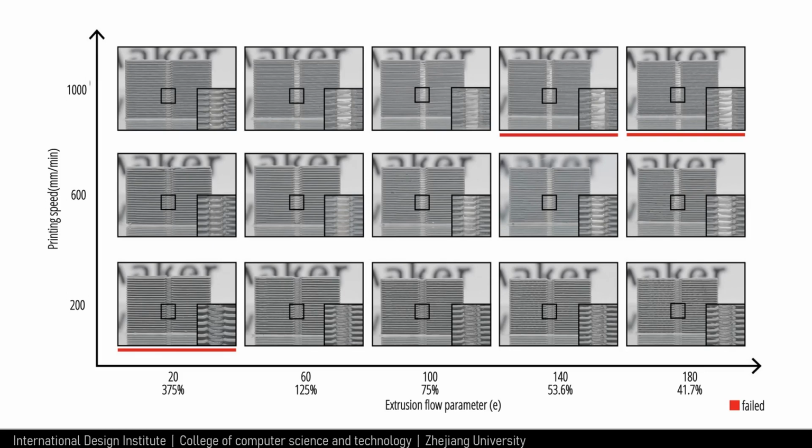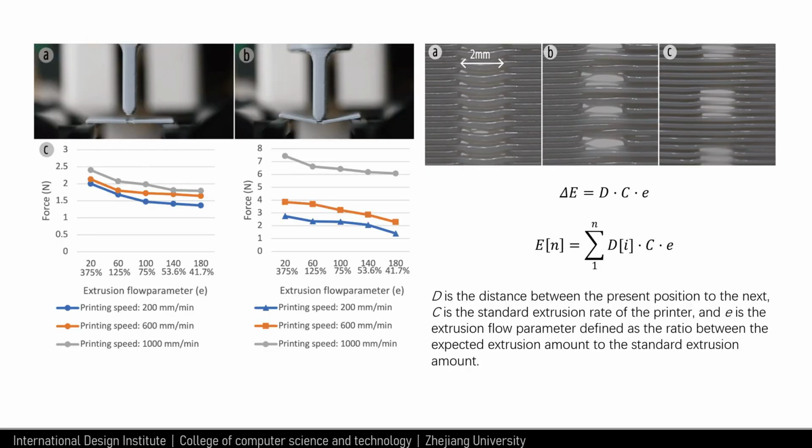We conducted a series of tests to determine the optimal parameters and their interplay for X-Bridges. Among all the parameters, bridge density, extrusion flow rate, and print speed have a dominant effect on the physical properties of bridges. We also use quantitative experiments to distinguish plastic deformation from elastic deformation, together with an extrusion control algorithm to calculate the extra filament for relative extrude mode for further G-code generation.